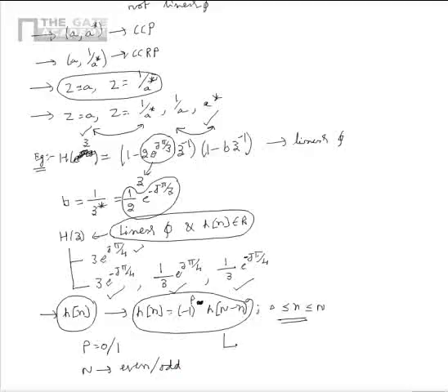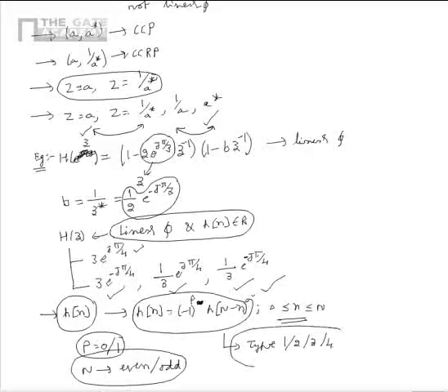We can classify the linear phase systems as type 1, 2, 3 or 4. So given a linear phase system whose impulse response satisfies a condition, depending on the value of p, that is 0 or 1, and the nature of N, that is even or odd, we can classify the linear phase system into four types as shown.